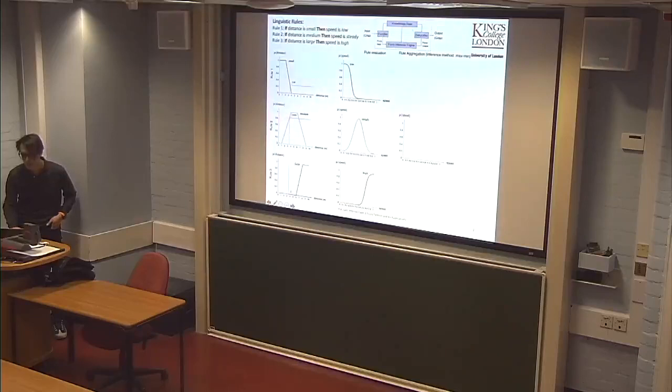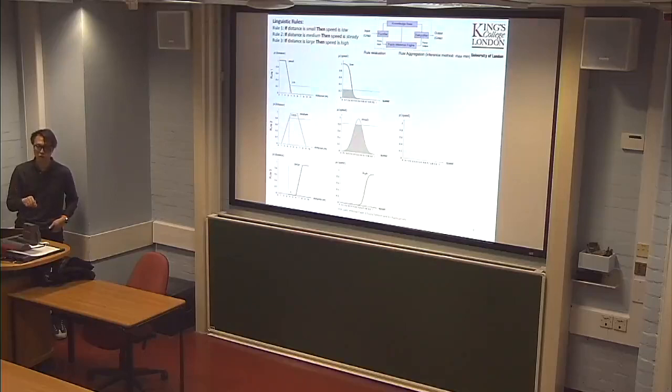Okay. And now we are at this point, the implication, and then we draw our horizontal line, and it tells you how low the speed should be, that low. Okay. How steady the speed should be, that steady. Okay. So we are going to highlight the gray area. That is the individual decision made by each rule. So we are now at this point making the individual decision by the fuzzy inference engine. And now we are going to combine all these individual decisions to come up with the final output. Okay, that is the way. This y and x axis is actually the same as this one. I just simply put it in a separate figure and drag this gray area into this one to represent the output from the first rule, and then the second rule, and I'm not quite sure whether you can see that, yeah.